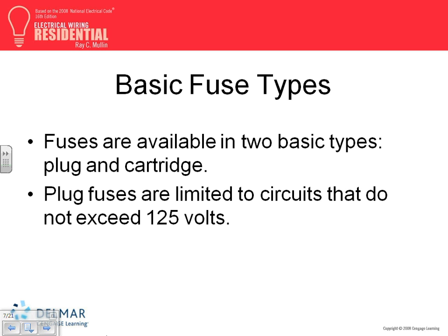Basic fuse types. For the most part, you only need to know about one type, the cartridge fuse. The only type you want to worry about is the cartridge fuse. The other is the plug-in fuse, these tiny little ones that you screw in. They're rated for 120 volts and limited to 30 amps. These are the old panels that used to use them, screw-in fuses, mostly to protect small loads.